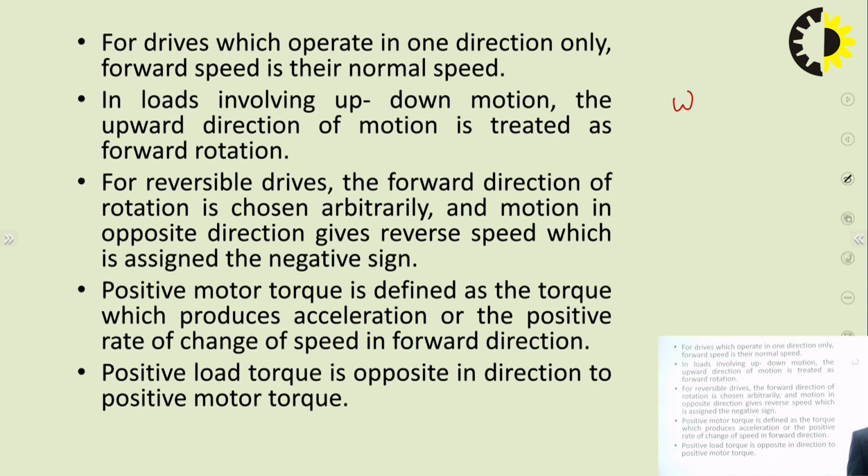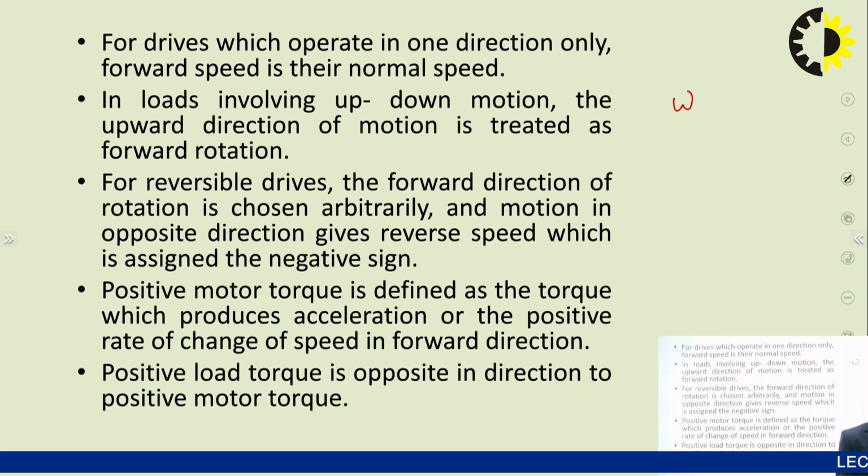In loads involving up-down motion, the upward direction of motion is treated as forward rotation, and downward direction is treated as negative direction or reverse operation. For reversible drives, the forward direction of rotation is chosen arbitrarily, and the motion in the opposite direction gives reverse speed, which is assigned the negative sign.